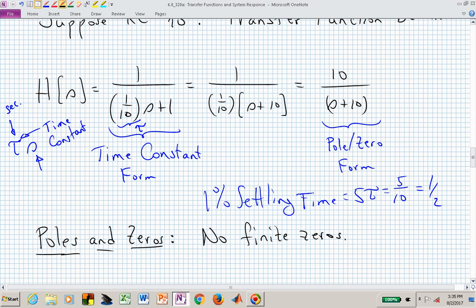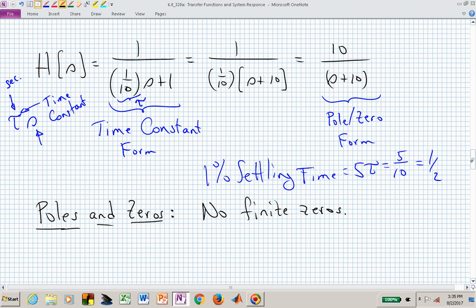What about poles? Well, we better expect some poles. We had a first order system. We had one derivative in our time domain expression. That led to a first order denominator. So we should have one pole, and we do. We can now find one value of S that causes that denominator to vanish, and that pole is now at S equal to minus 10.